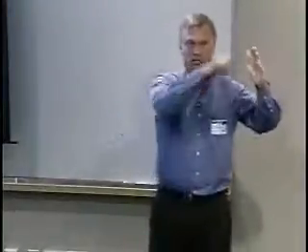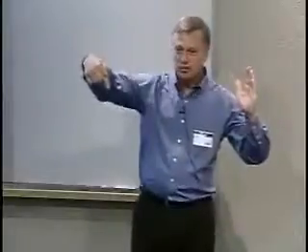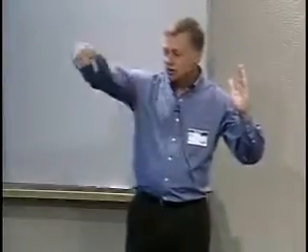we allow concurrency even at the continuous time level. If you have an artificial potential in the form of a bowl structure, and your policy is to descend it greedily, then you want to go down the gradient of the bowl. That also means that there's an isolevel curve around the bowl that says you didn't make any progress towards the bottom. Right? It's orthogonal to the greedy descent. And so if you're going to go greedy on this bowl, another bowl can tell you another action to go in, and you project that onto the isolevel curve. It means it doesn't destructively interfere with the first priority controller at all.